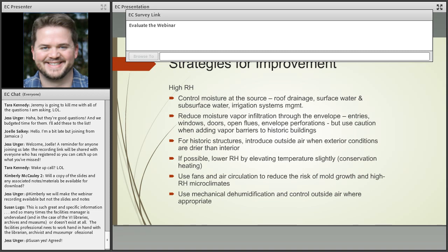Where we're at today is recognizing that as long as we're not bringing the unconditioned air in, as long as, i.e., we're not negatively pressurized, we're pretty much okay. So we look for more of an equal recirculation operation where we're at equal or neutral pressure, if you will. And the key to this is that we send the same amount of air into the space as what we bring back out of it in terms of total volumes.